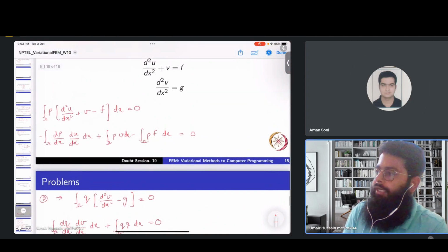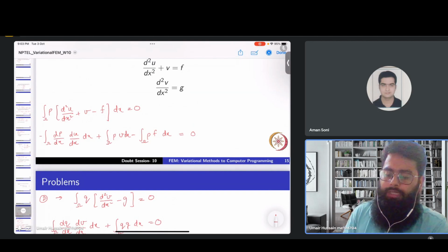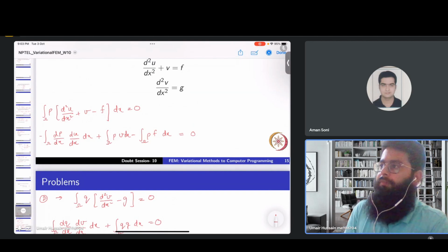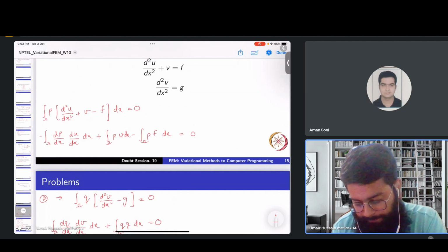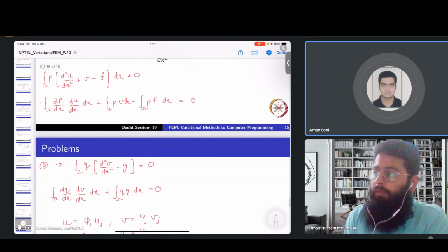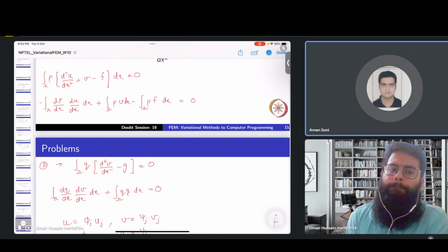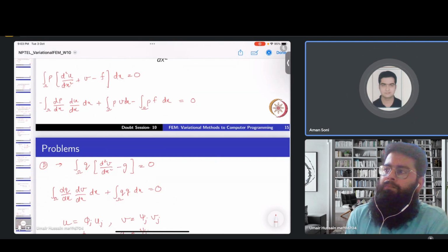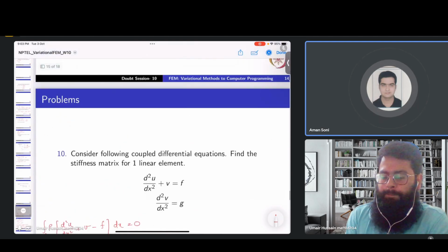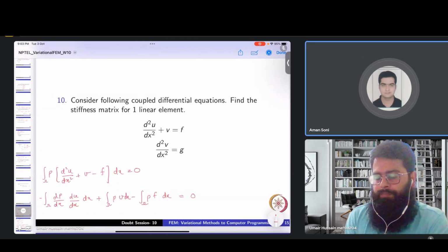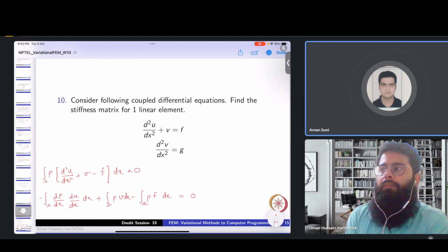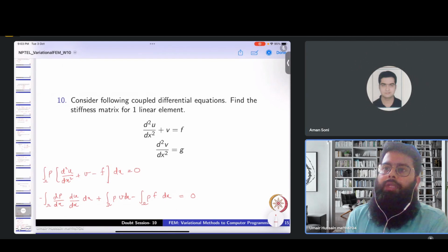In the elasticity equation, we don't break it down into two equations and solve it. There are ways to deal with it directly, but in usual coupled problems, we have to do it this way. So coupled means there are two types of analysis. For example, first I want to distribute the temperature within the FEM structure based upon the boundary condition, and then again I will use this in the static structural analysis or transient structural analysis to get the stress results.